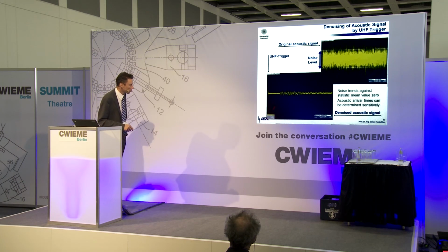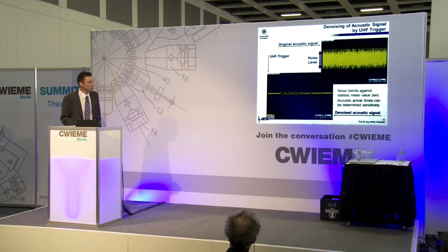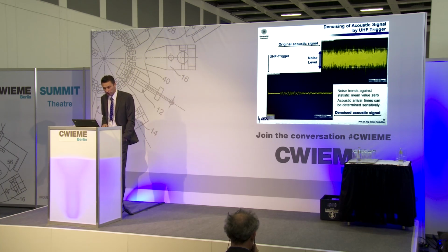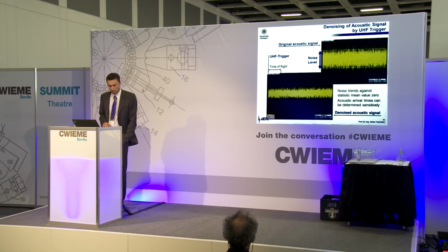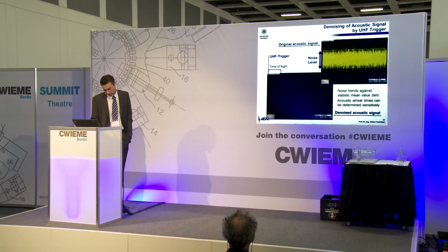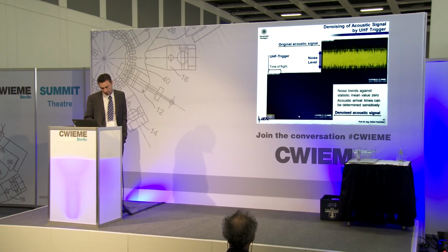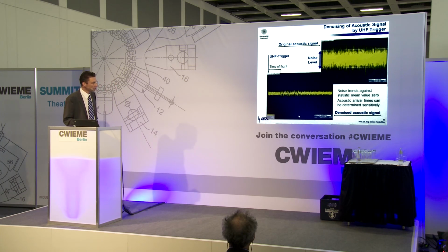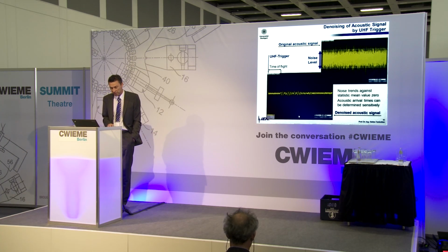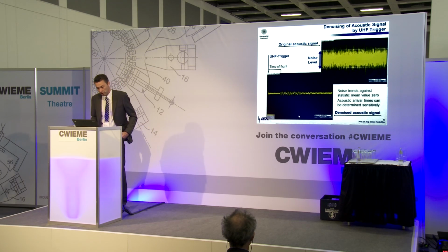So we have here now more than 100 signals averaged, and now you can see this was a UHF trigger signal, so the acoustic wave needed this time until it arrived at the sensor. And this is now the flight time of the signal. And you have to use this flight time, of course, in order to find the spot where the partial discharge occurs.